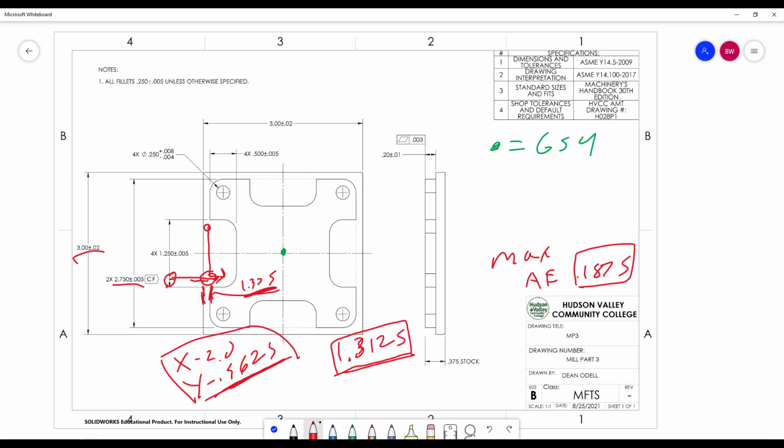If we zoom in on this, if this is the wall, we want the cutter to be here, and we want this to be there, 0.0625. Okay, so we need to take into account the radius of the cutter. So we are going to focus using comp on the outside of the cutter. Okay, but we're going to program like we're here, which is much easier in the math.